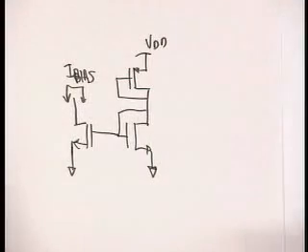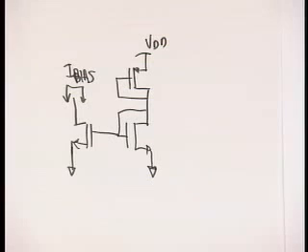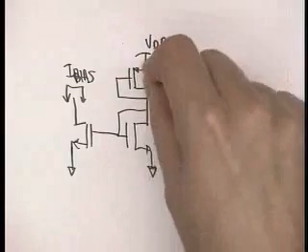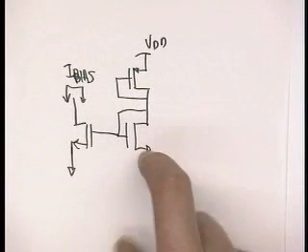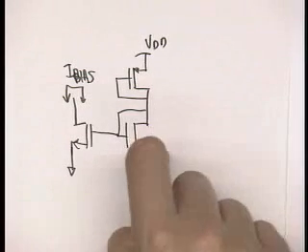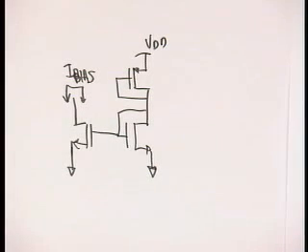So generating your master bias by putting a couple of diodes back to back or something like that. And you did that because that's the lowest area kind of circuit you can do. Now, in reality, this is a very area efficient circuit, but it's not a very supply robust biasing circuit. As supply goes up and down, that extra supply shift needs to be dropped over the VGSs of these two devices. So therefore, the VGS increases, so the current increases. This is very supply sensitive. So you probably want to come up with some circuits that are less supply sensitive.